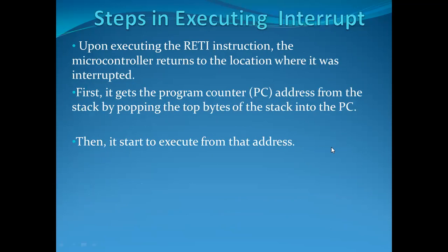Upon executing the RETI instruction, the microcontroller or processor returns to the location where it was interrupted. First, it gets the program counter address from the stack by popping the top bytes of the stack into the PC. Then it starts to execute from that address.